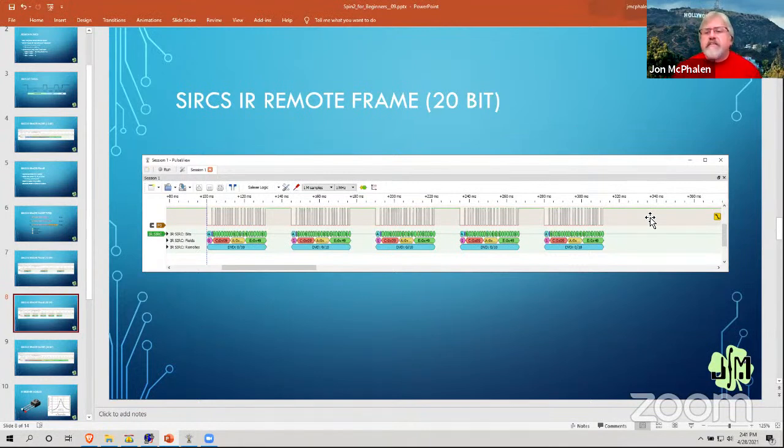And it obviously gives me even a little more leeway technically, because we don't get the first value until about this time frame. So if we receive a value here and then wait 250 milliseconds, we're going to be somewhere out here before we'll even think about looking at another button. But that gives you, from a human standpoint, time to press and release the button without any problems.